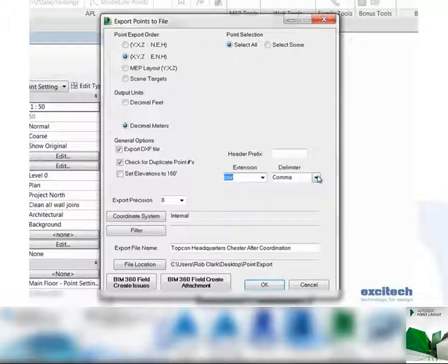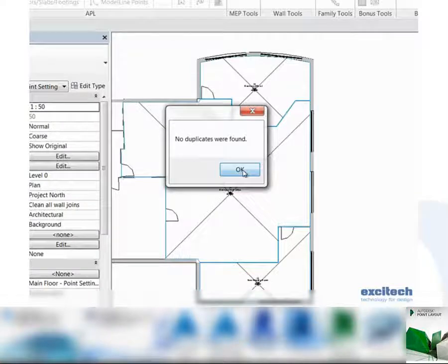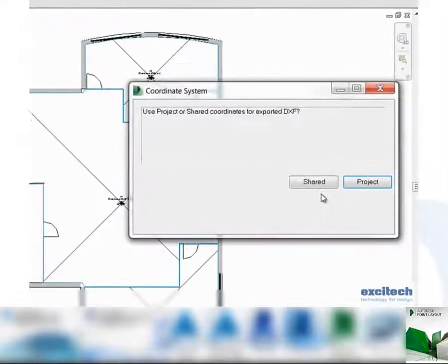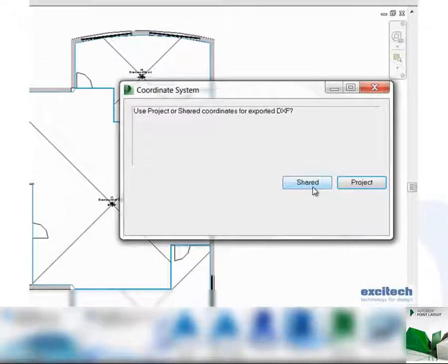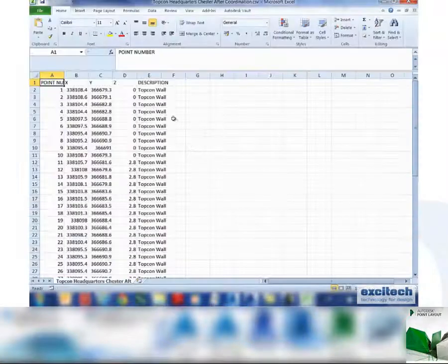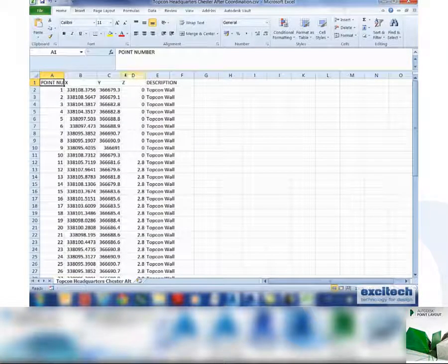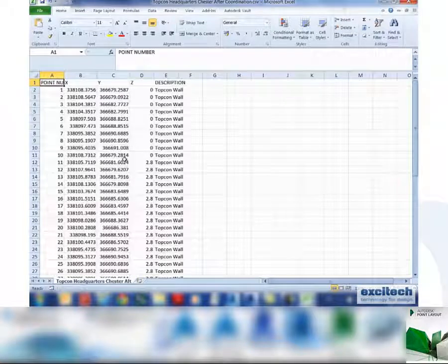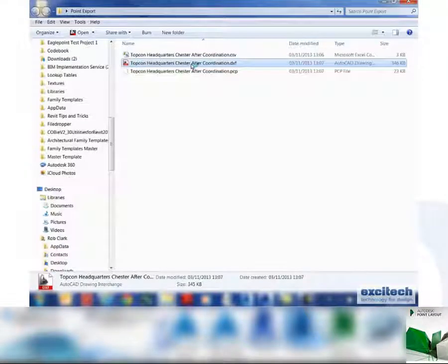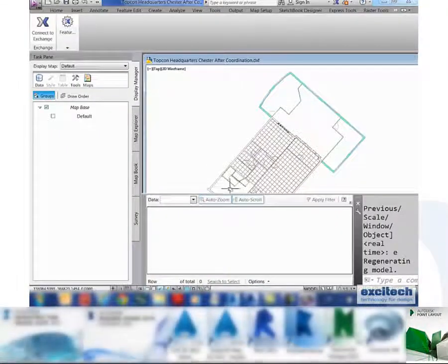So one of the things you can do if you work with certain providers of site equipment is send this file over an internet connection to people that are working in the field. If they've got the right sort of surveying equipment, they'll be able to download that into their equipment and find those same locations on site. Equally, there is an import option, so if they need to mark out any positions on site which they need the designers or the construction management team to understand within the Revit software, they're also able to do that as a backward workflow as well.